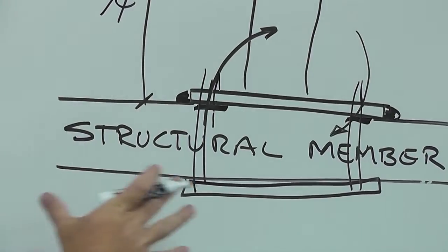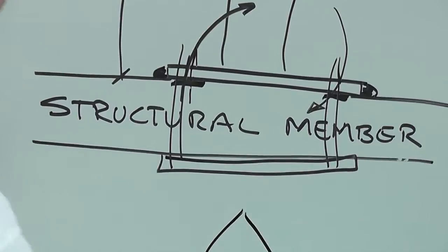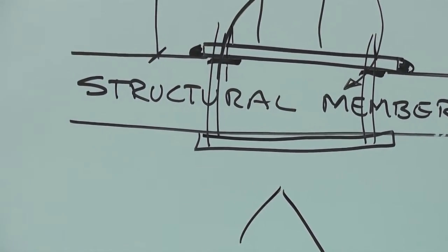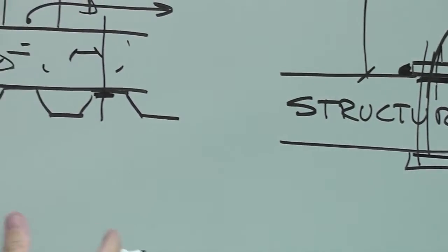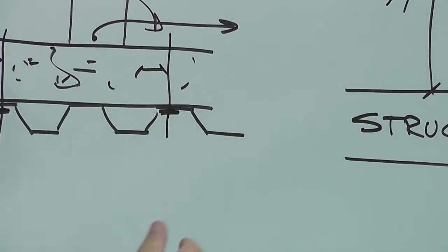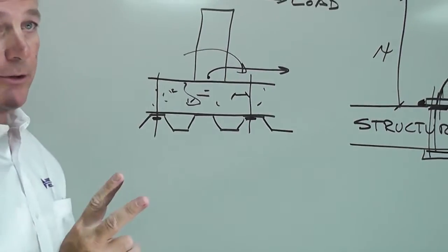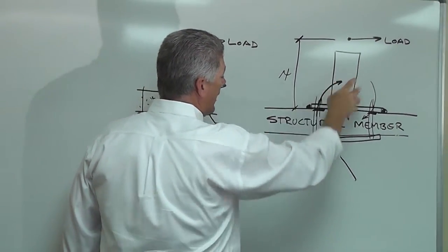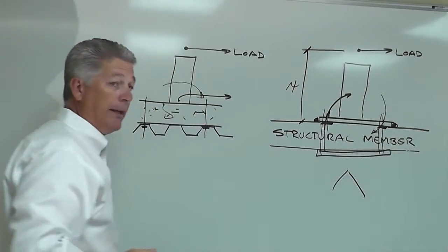The problem that you run into with this type of design is you have to have access to the underneath side of the beam, which means if this is located in a part of the building where there's a finished ceiling or a drop ceiling, a lot of times this is not accessible to the underneath side. This is no longer a 1-person installation, this is a 2-person installation. One to handle the heavy load of the rigid post on the top side, and another individual on the underneath side to mount the lower plate.